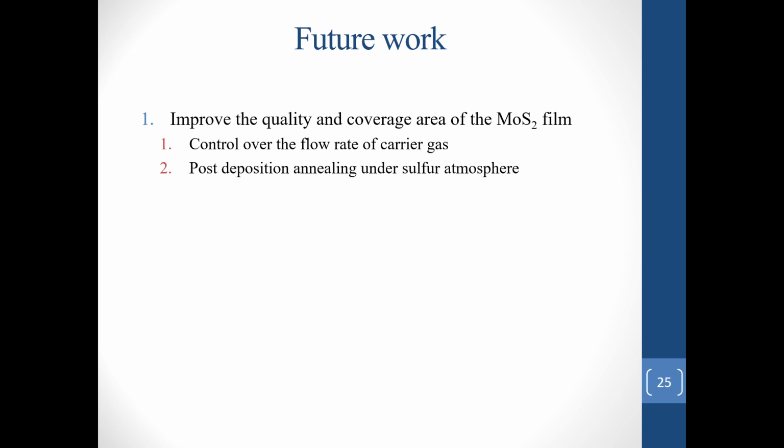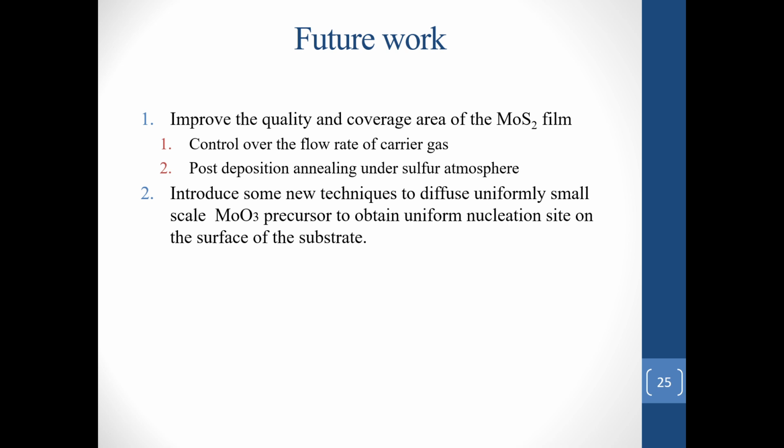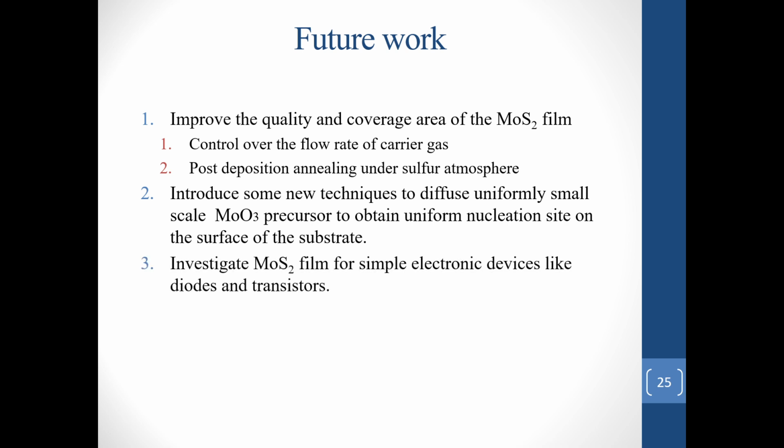For that we have to control the flow rate of the carrier gas, do post-deposition annealing under a suitable atmosphere, and introduce some new techniques to diffuse small-scale MoO3 precursor uniformly to obtain uniform nucleation sites on the surface of the substrate. We also want to investigate MoS2 film for simple electronic devices like diodes and transistors.